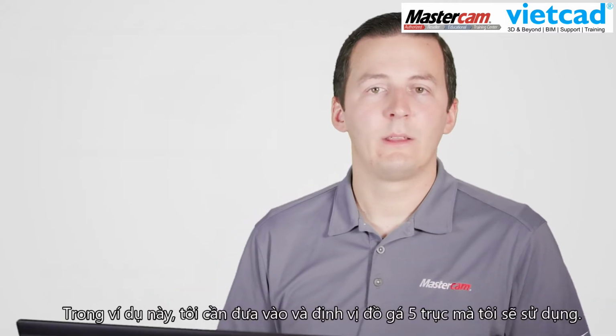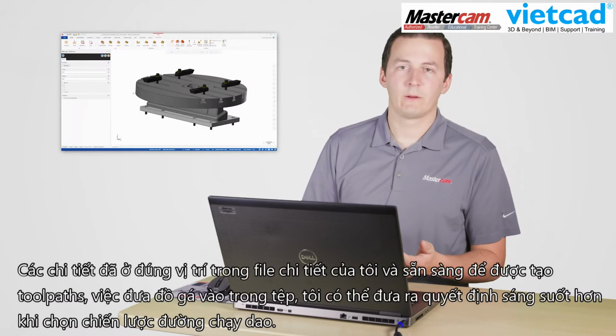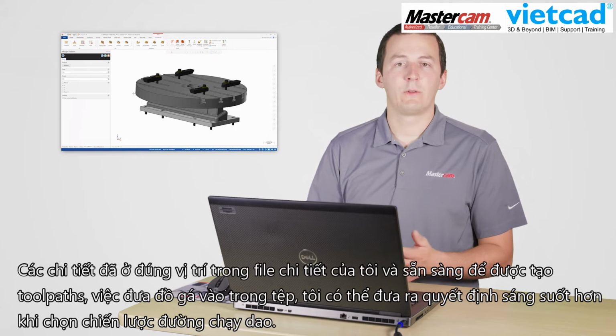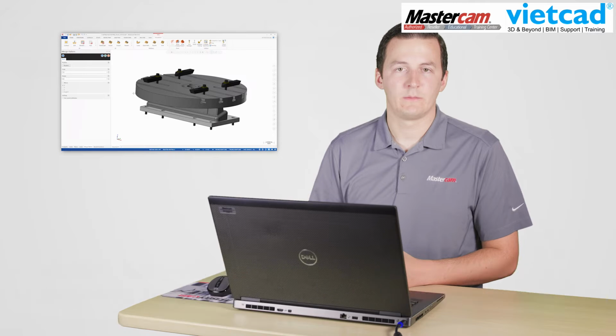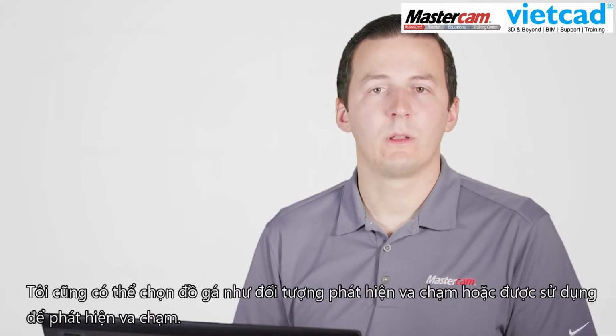In this example, I need to merge and position the 5-axis fixture I'll be using. The parts are already in their final positions in my part file and ready to be toolpathed, but by including my fixturing in the file, I can make more informed decisions when choosing my toolpath strategies. I can also select the fixturing as avoidance geometry or to be used for collision detection.